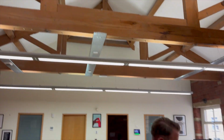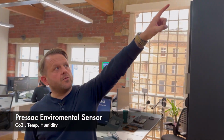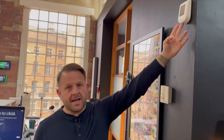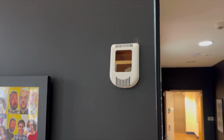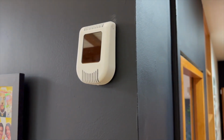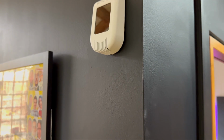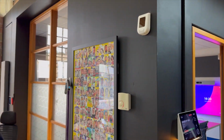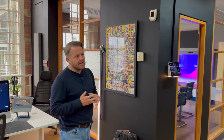And then as we start to move through the office, we have a sensor here which does temperature, humidity, and CO2. So it's a combination sensor. The difference here is this one runs on the EnOcean framework. So this is using a low-grade transmission protocol. These sensors themselves are powered by ambient light. They're not powered by battery. So they are a big win in any kind of sustainability play, and they last for a long time because the batteries aren't in use.